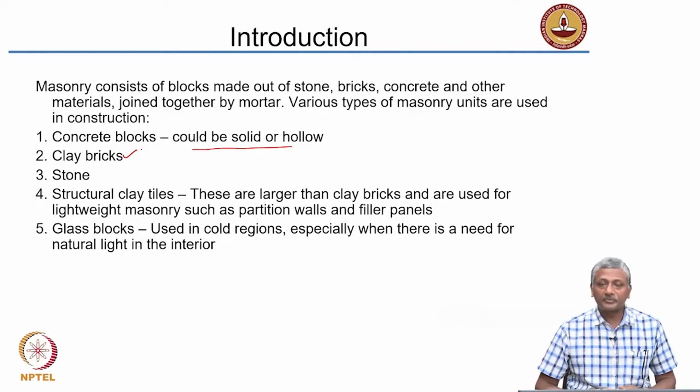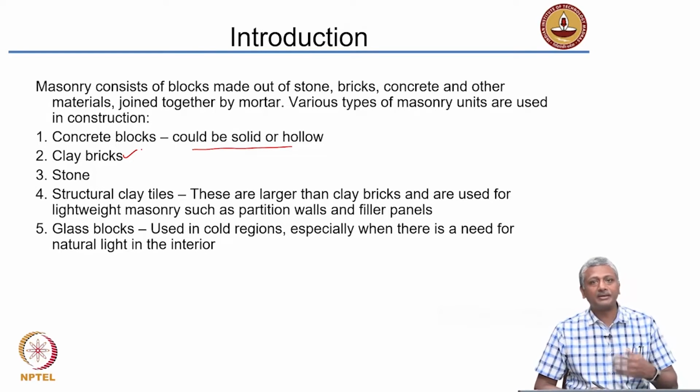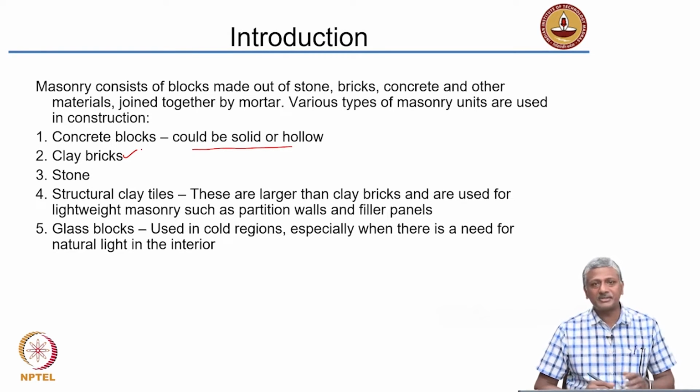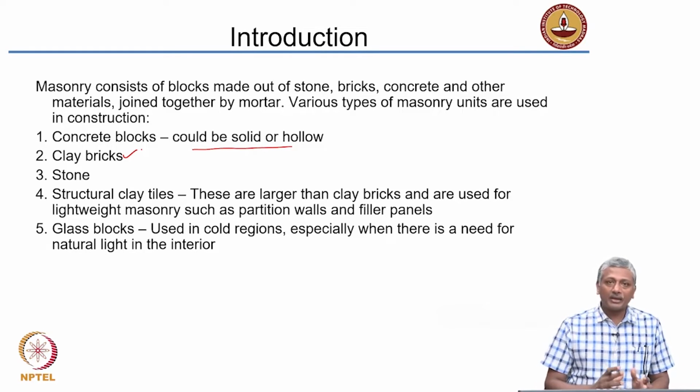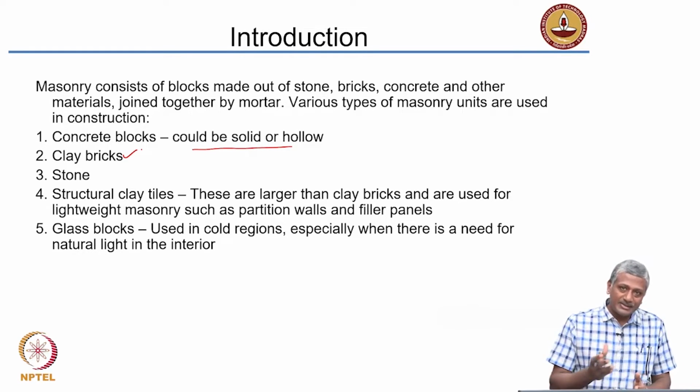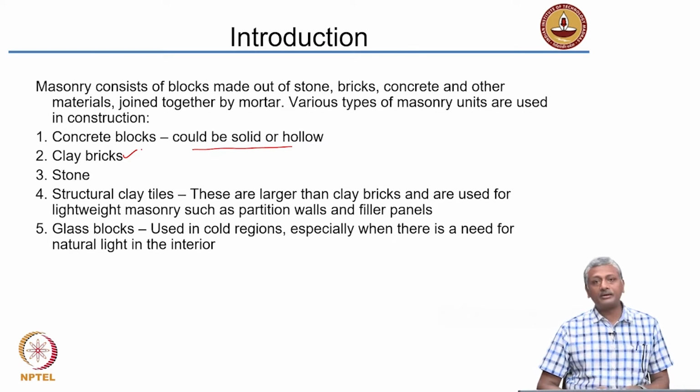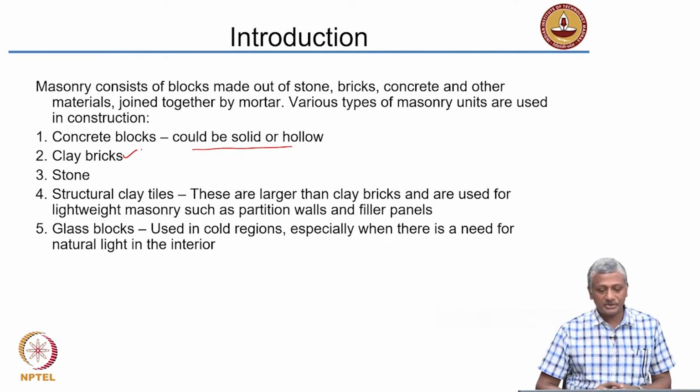Apart from these, there are also structural clay tiles. You can actually make structural clay tiles to bear load. So in masonry, the components are bearing load. A typical tile which you put on the floor is not bearing so much load as a block that is supporting a wall. So structural clay tiles are designed to be larger than clay bricks and can be used for lightweight masonry such as partition walls or filler panels.